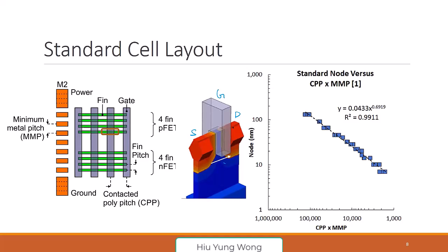So each of this is like a fin, right? The fin on the fish. So that's why you draw this green one, which are the so-called fin. And this vertical one are actually the source drain contact. And you can have several fin. Here have 4 fin for the PMOS. So you have 4 transistor width, right? And then 4 fin for the NMOS, right?